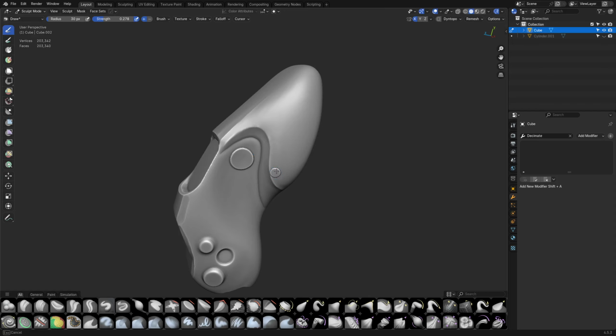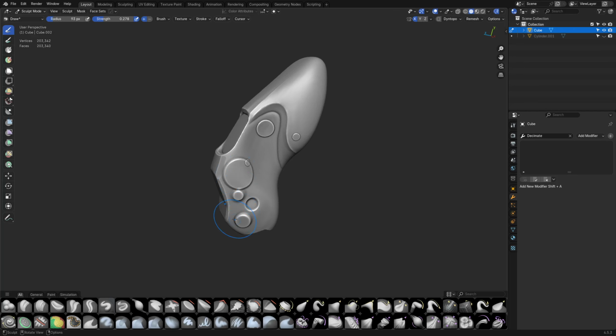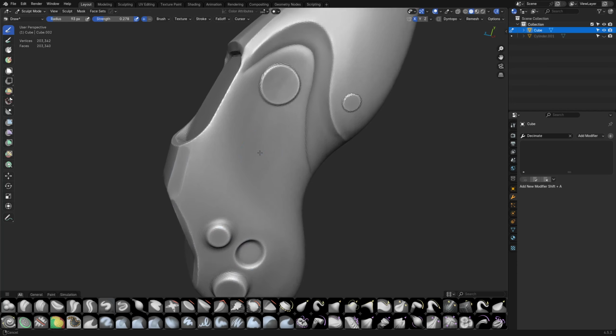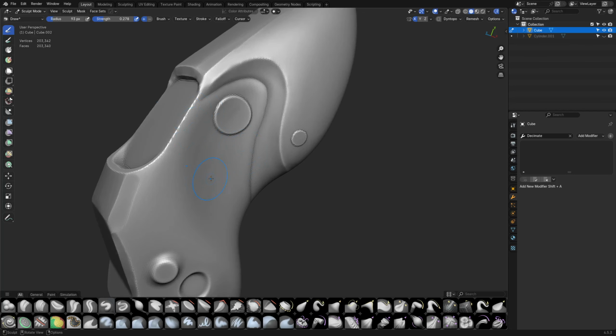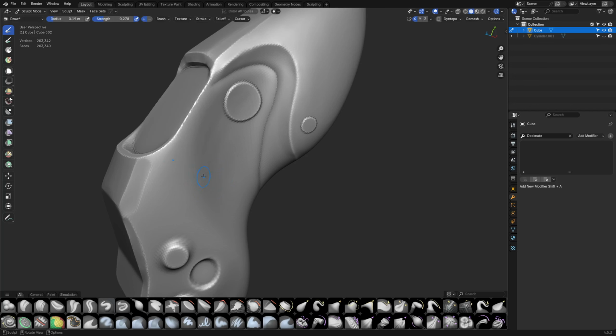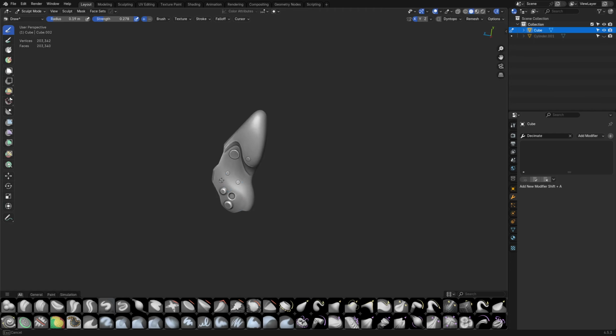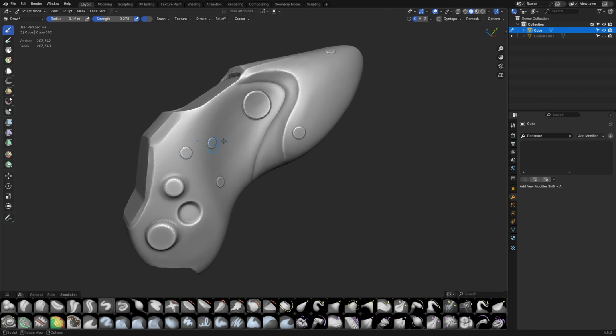Now someone's going to ask this, I've seen it before: can you keep the brush the same size whether you're zoomed in or out or not? Because as you can see, if we zoom in, it's this size. If we zoom out, it's this size. Big difference, right? Now, normally I would say don't worry about it too much, because Blender does have an option to change the radius here to behave differently. So we could do a scene setting, right? And we can change the size here. So we'll always have the same size, or so we think. It doesn't always keep the same size necessarily, but it tries to, and so it usually works out okay.